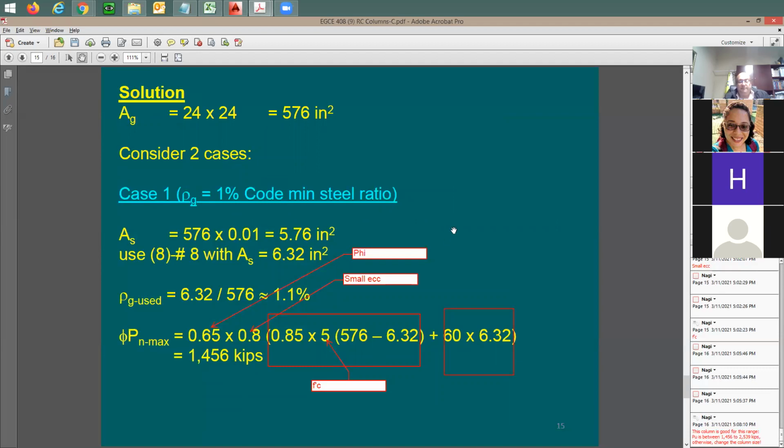You also still have steel strength, right? We can also increase it, right? Yeah, but it's gonna be kind of tough to find different grade of steel like 75, this is not easy. But yes, if someone says grade 75 is available, you're gonna say, okay, let me try grade 75. But most likely this is gonna be kind of tough to find.